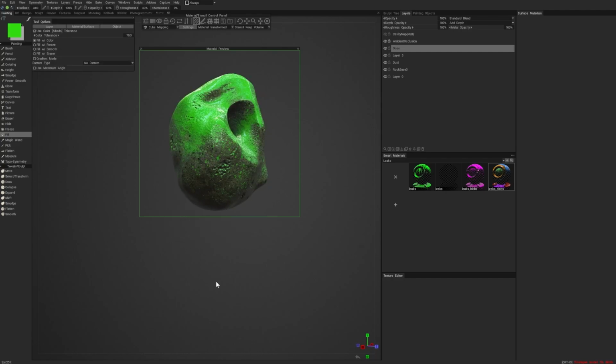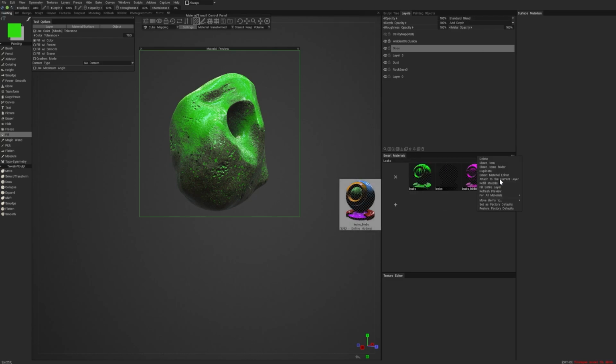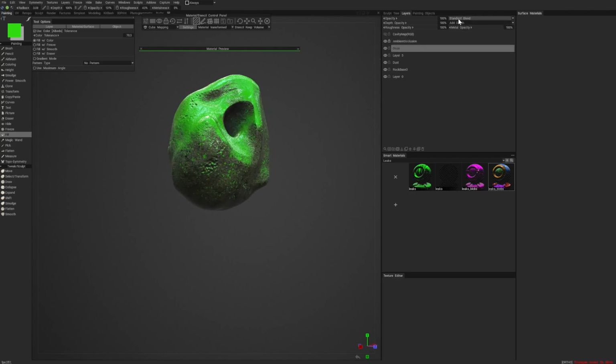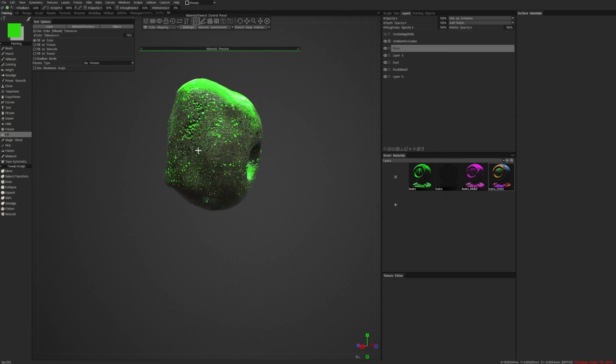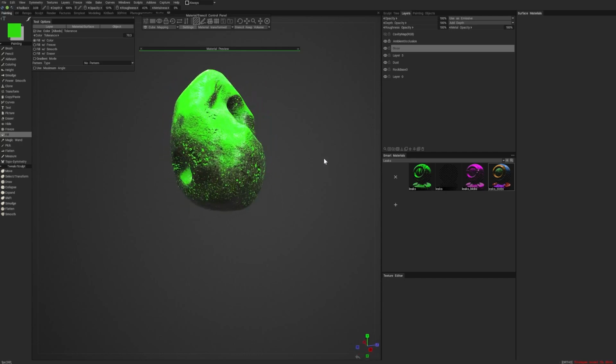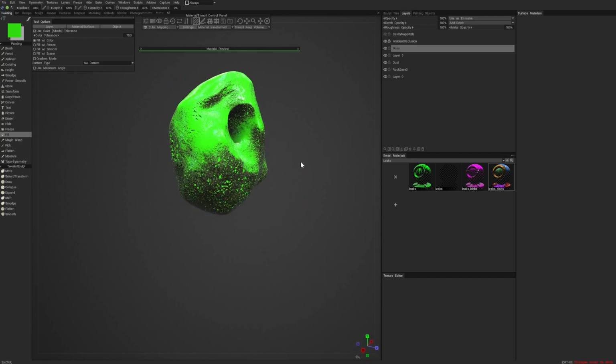You can press the B key. Oh, some of these hotkeys are not showing up for me. Anyways, so we can have something like this, and we could add that ooze to a layer. And you'll find we can actually apply it. So I can, whoops, right here, fill entire layer. Okay, and then where it says standard blend, if I wanted to, I could do things like use this as emissive. So I could use that as an emissive map, in which case this would export as a glowing material when I use this in a rendering engine.